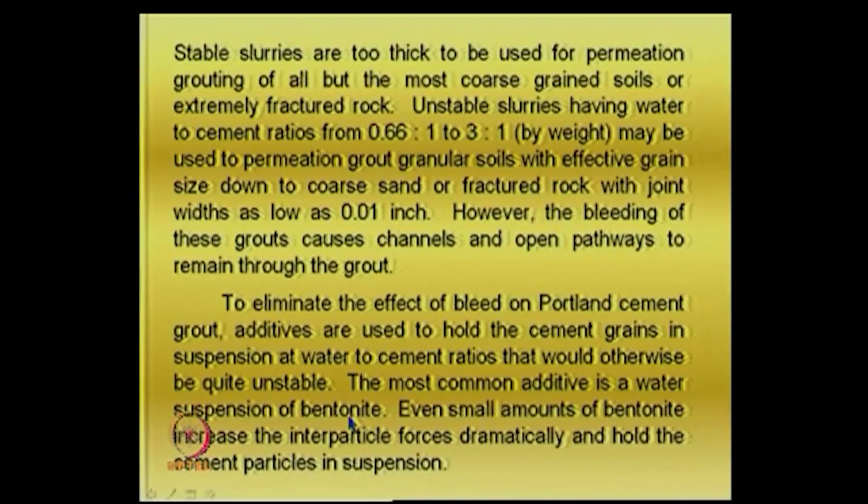We know that bentonite is more like a repelling agent. The attractive forces are very minimal there. Bentonite particles tend to float easily in water, and when you mix it with cement, it has a very good advantage. Even small amounts of bentonite increase the interparticle forces dramatically and hold the cement particles in suspension.